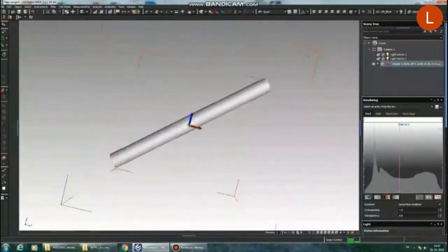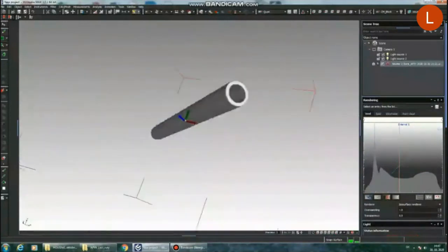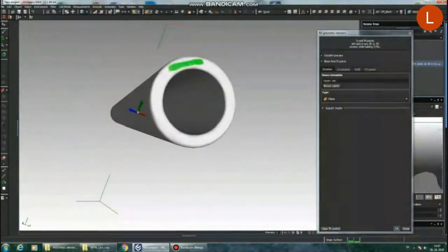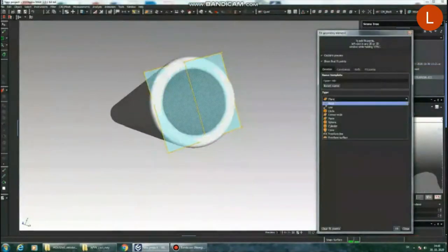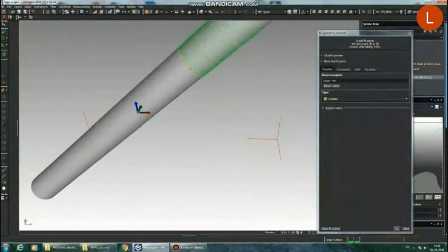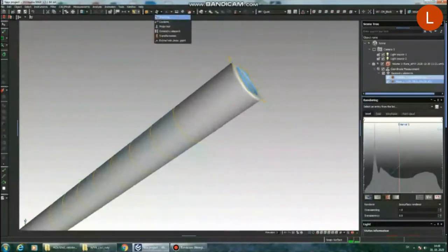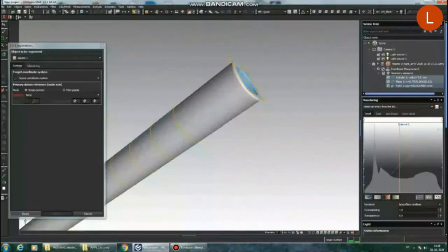From the surface recognition process, the 3D model of the part with its internal structure is obtained. The part can be rotated, zoomed, and recognizes elements such as plane, cylinder, and other geometrical definable elements from which it is possible to create sections, projections, and connections into one element.